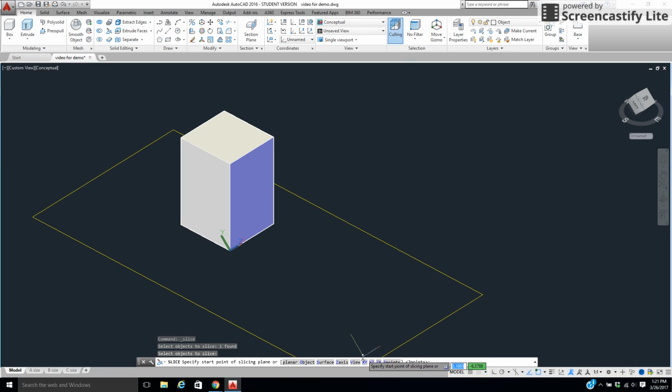So I'm coming down here to the screen where I can see X and Y, Y and Z, Z and X. It's my X and Y. I'm choosing that. Now it's asking you, specify a point on the XY plane, 0, 0, 0. Well, 0, 0, 0 is right there because that's where I set my UCS to start with. That's why I do it this way. It cuts out the middleman. So by doing this, it says 0, 0, 0.